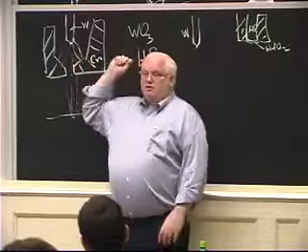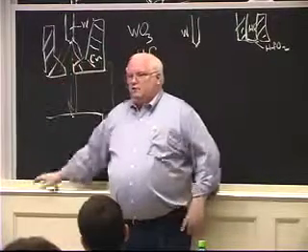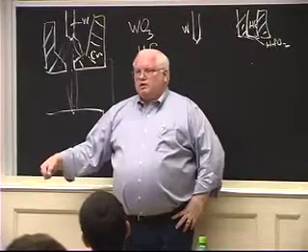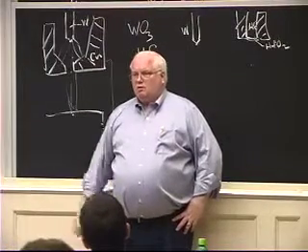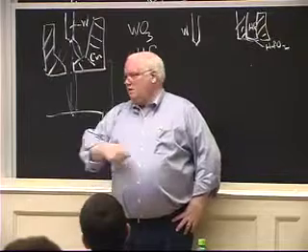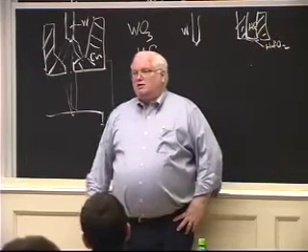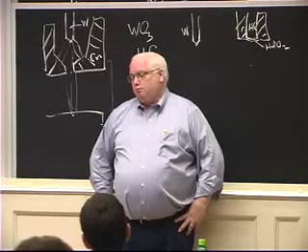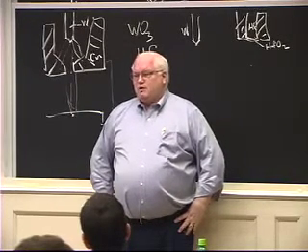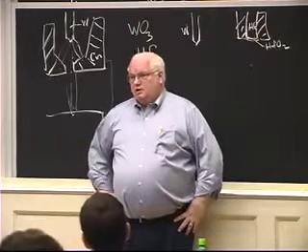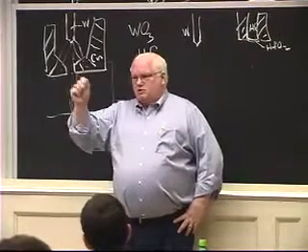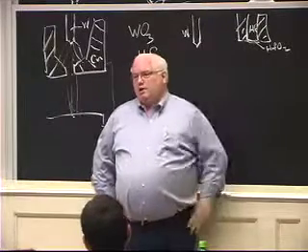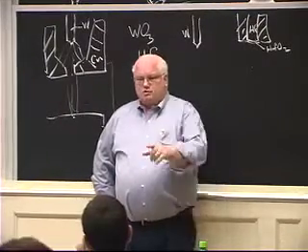These guys with the hafnium may only be generating 15 or 25 amps, but they'll cut through sheet metal just great. It's on a little portable thing, probably weighs 20 pounds with a handle. You can plug it into 110 volts, have compressed air, and you can now cut sheet metal at the speed of plasma cutting, which is faster than you can do with oxy-acetylene or anything else. So now sheet metal workers, people putting in ducting and stuff, they've got these little plasma cutters. And it's all because of the development of the hafnium electrode, which will survive oxygen.